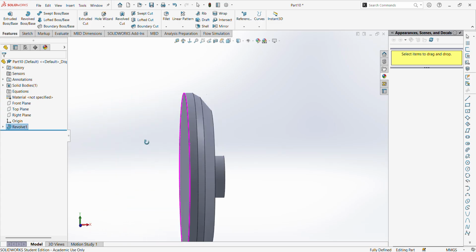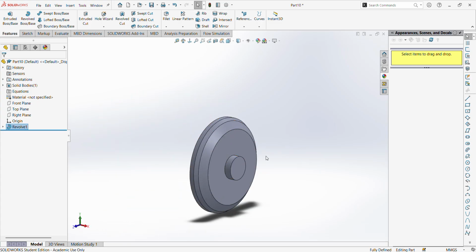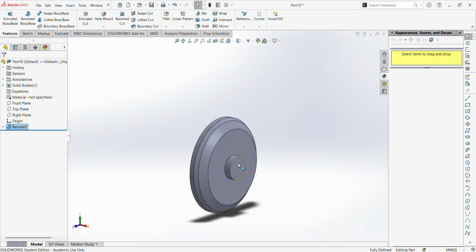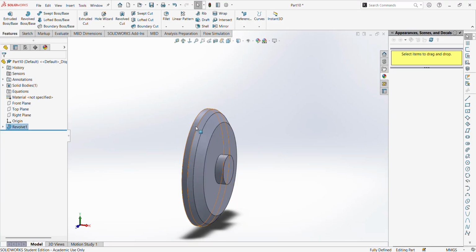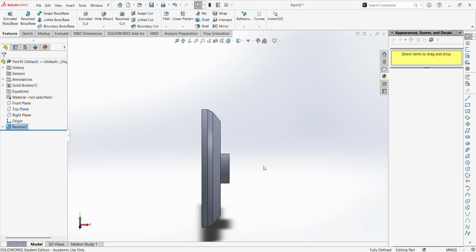And now look how much more interesting these pieces can get. Let's think back to our last example where we extruded a couple times to get out to that point. Would you want to do one disc extrusion of 10, a draft extrusion at 30 degrees of however distance, another draft extrusion at 50 degrees, and then another extrusion at 10 with no draft?